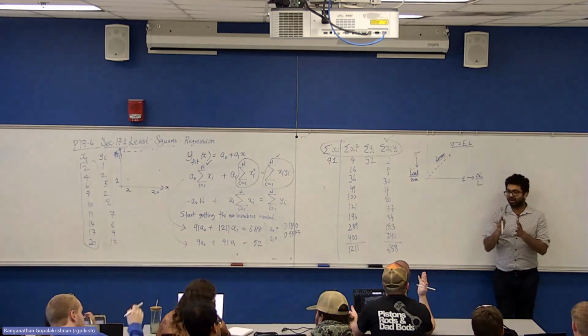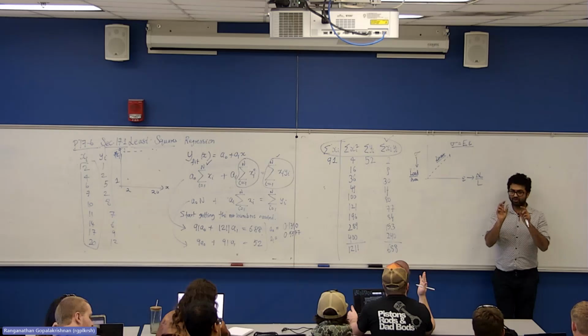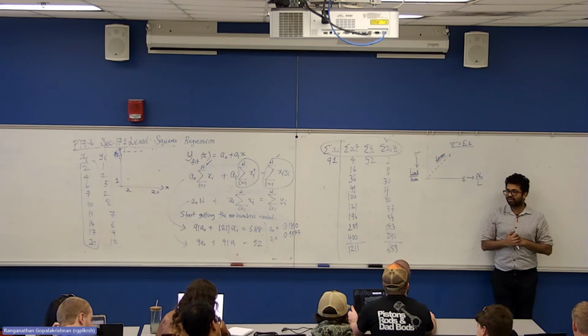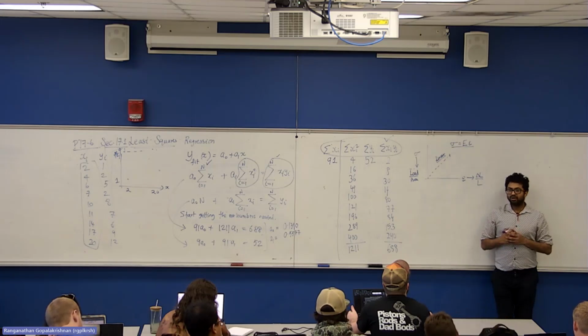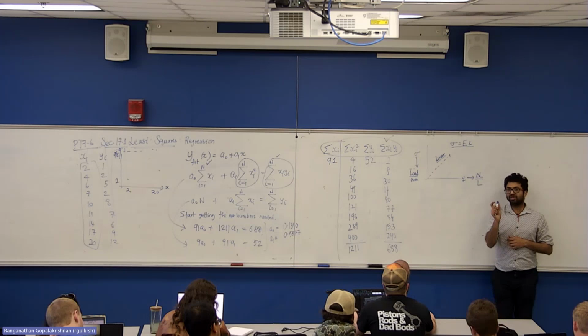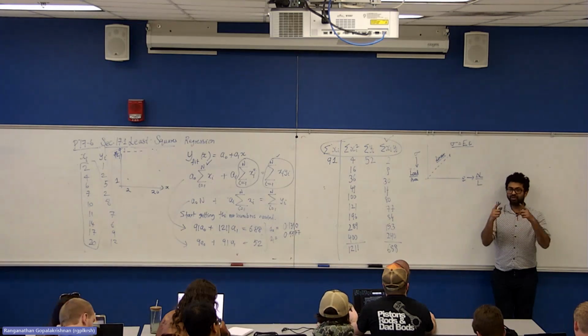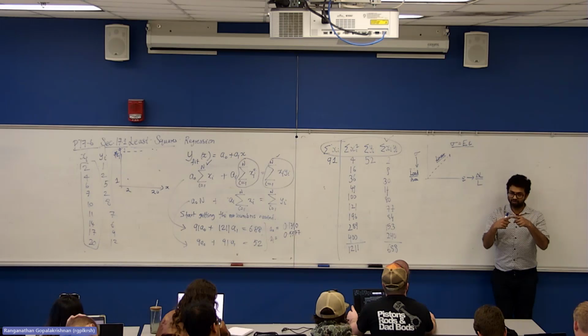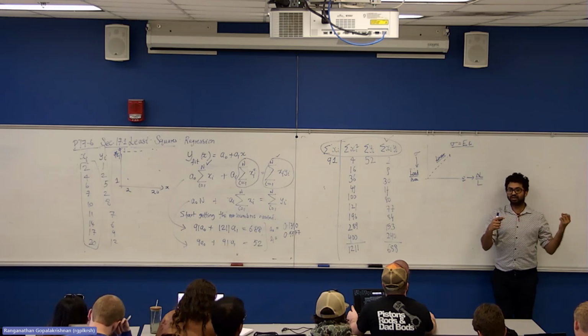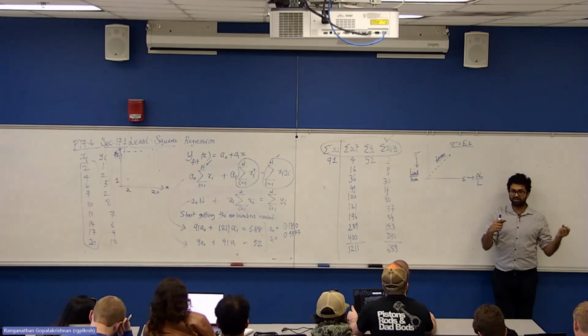Can anybody tell me how exactly the thermocouple gives you a temperature readout? What exactly does it measure and how do you get a temperature readout in the end? Yeah. They measure voltage, right? Or they give you a voltage readout? They actually sense the voltage because if you bring two dissimilar materials in a temperature difference, it will produce a voltage. And that voltage is calibrated against a temperature standard to get you temperature.